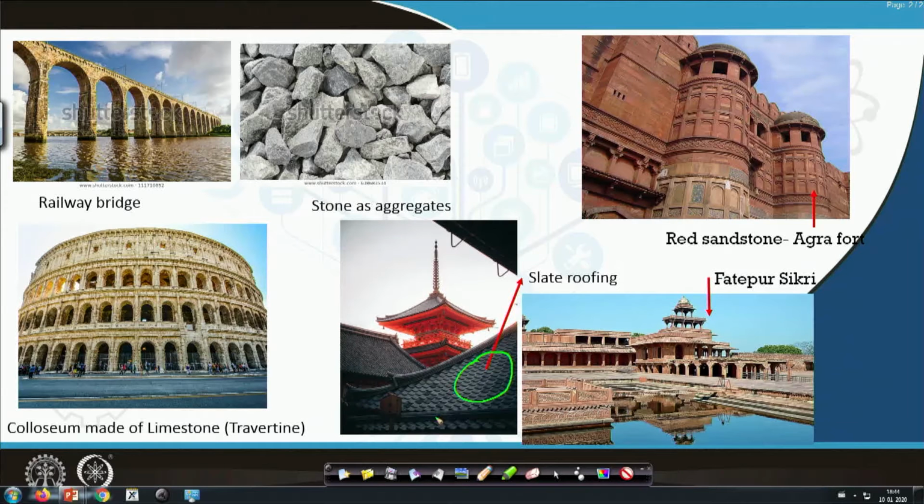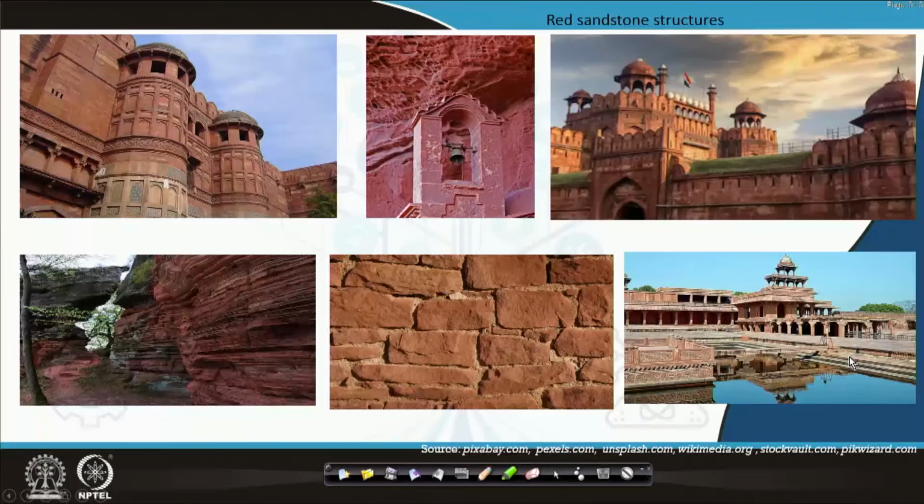So, the lowest one is the bottommost and the starting point, and on top of it they are sitting. Even there is an overlap at the edges, so no water can seep in. Usually this arrangement is done on top of a wooden support system. Again, wood is also an insulator, thermal insulator. So, electrical insulation, thermal insulation and overall insulation of the hillside sloping house. Here are some more pictures demonstrating sandstone as a building material, stone as a building material.